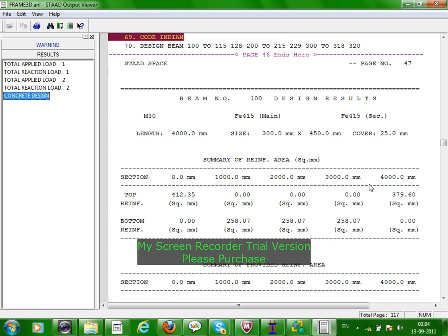3 and 4. This is calculated at one quarter of the section. What is that? Over here the top reinforcement is not required. It is better to check the bending moment diagram, then we know. At the support you will find the negative bending moment. To compensate the negative bending moment, you have negative reinforcement. In between over here you will not find any moment, that's why no reinforcement. And due to the downward moment you will find this reinforcement.